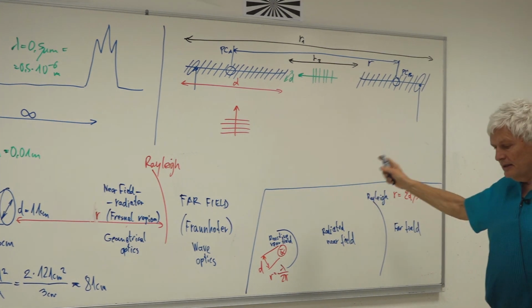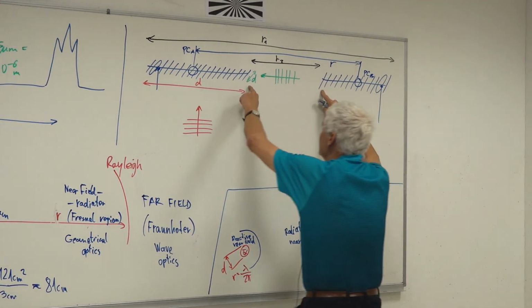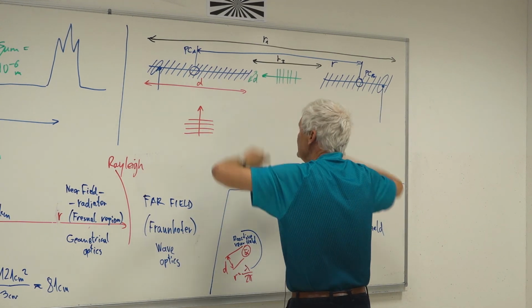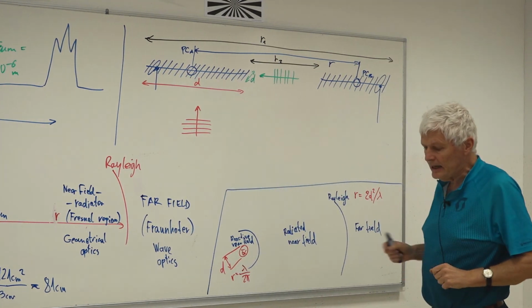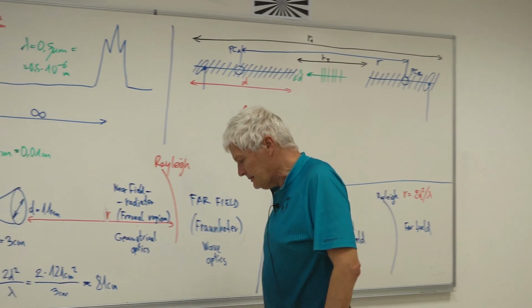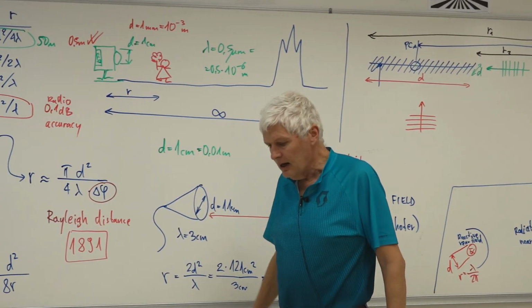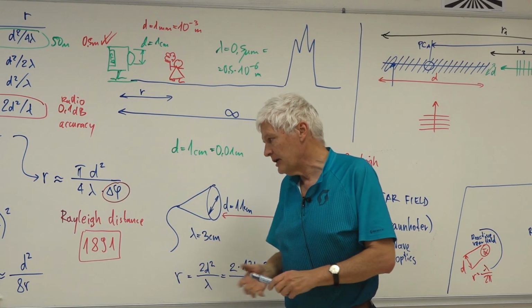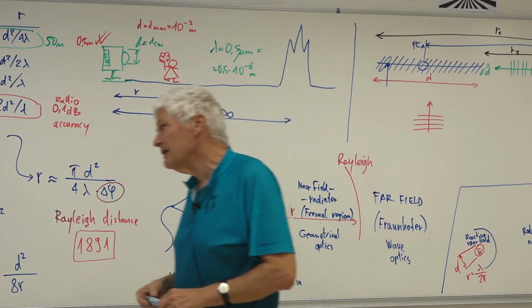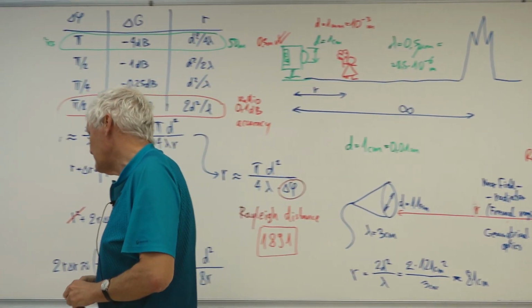So measure the distance not between the beginning or the end of the antennas, but between their phase centers. With some antennas, it's easy to guess the position of the phase center out of the geometrical construction of the antenna. With other antennas, the phase center is not that trivial.